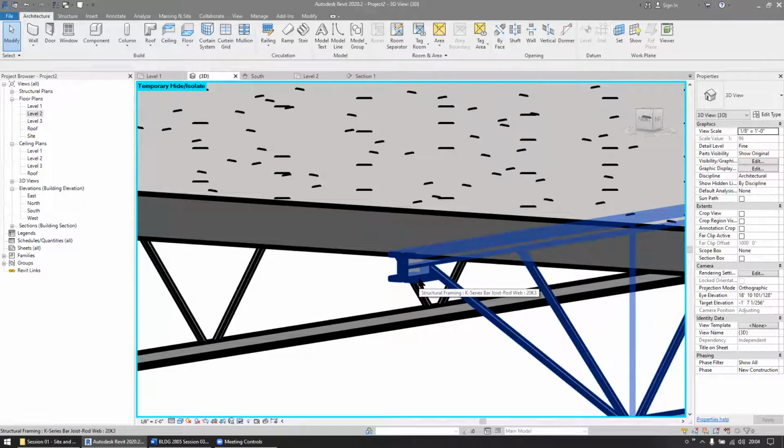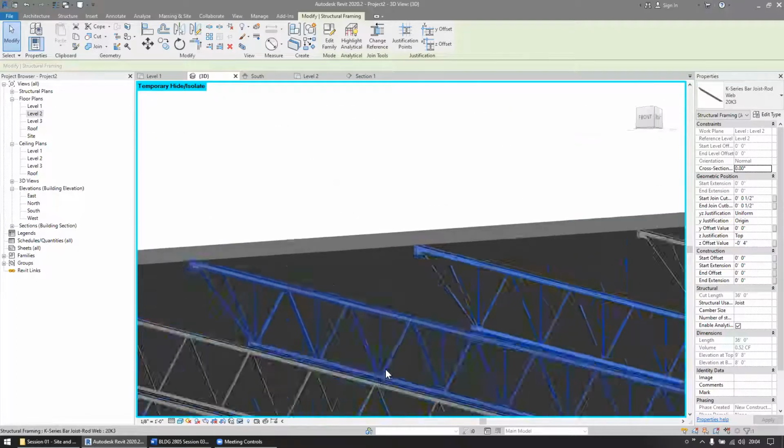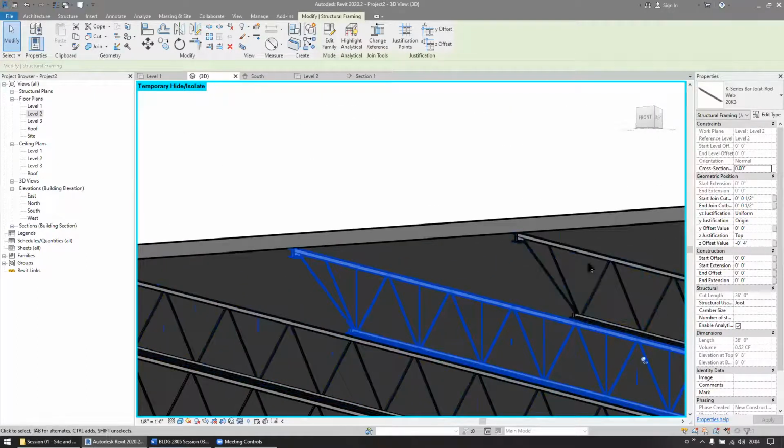So the bottom of that seat is supposed to sit on a beam. And then the top of that seat, well, that's the top chord of the open web steel joist, and the decking spans in between the open web steel joists. So those seats are 2.5 inches for smaller joists and typically 5 inches for larger joists.